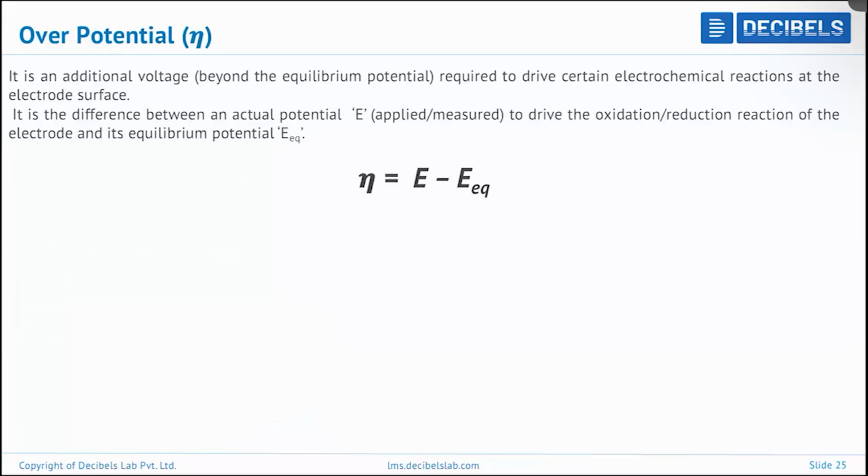All these things, I'll just skip this. Next, come to the important characteristics of the battery, that is overpotential. I have discussed the voltage in the Nernst equation. For LiCoO2 the expected voltage is 4.1 volt, but practically we can get only 3.8 or 3.7. That much voltage is lost during discharging, or while charging, that much extra voltage you should apply. That is called overvoltage.